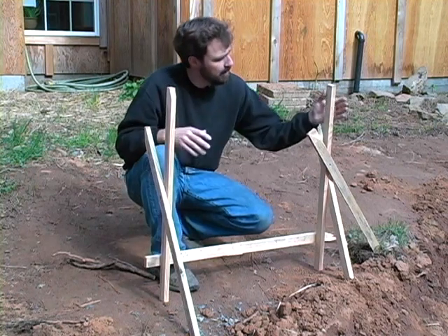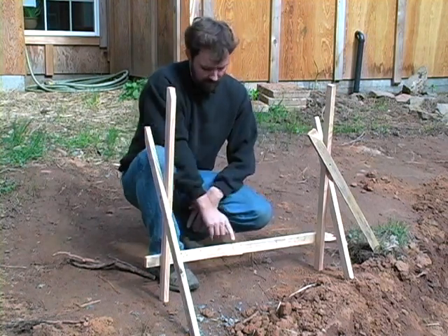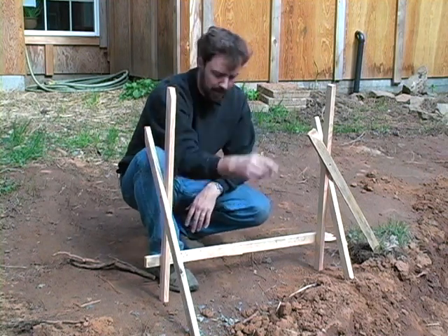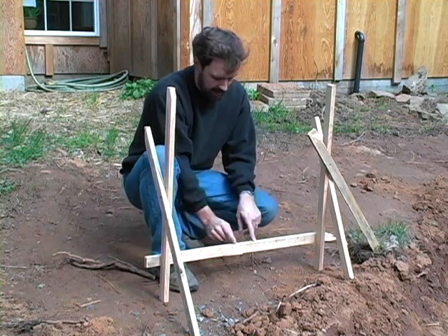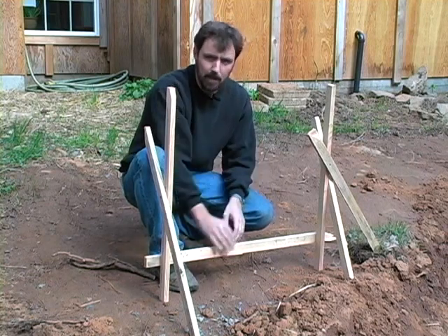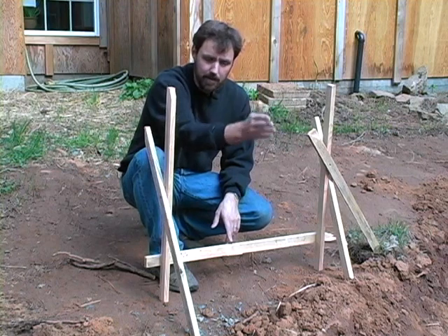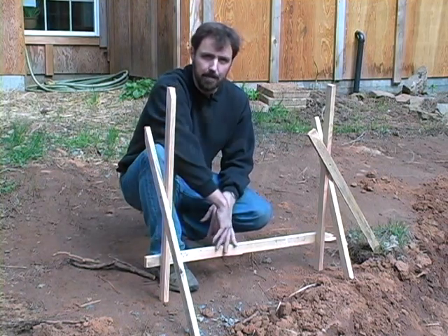So it's basically here we've got 3-foot stakes driven into the ground and braced in both directions. We have a screw on top. We can attach a string line and pull taut to the other batter board on the far side of this wall line. We can then move this screw, or we can add additional screws and pull our string to either side to get right on exactly where we want to be in our corner. It also allows us to get perfectly square in those corners.